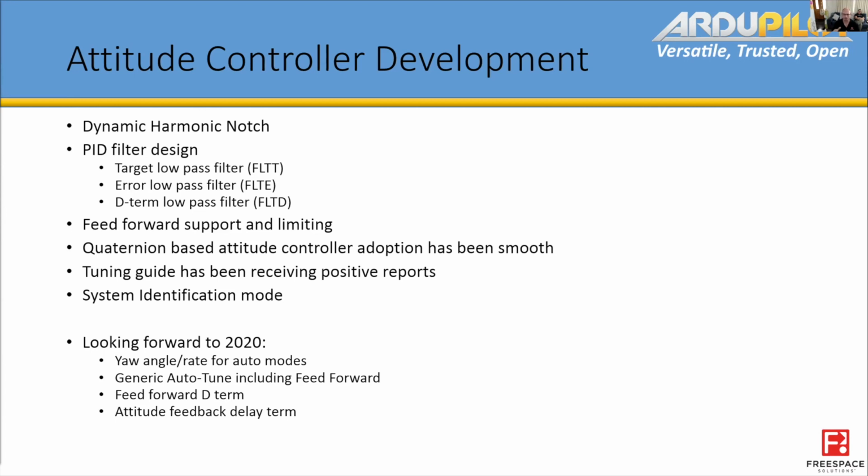We've taken that feed forward support in the motors and actually fully acknowledged that through the rate loop, and separated that out and appropriately handled it during large attitude error correction.